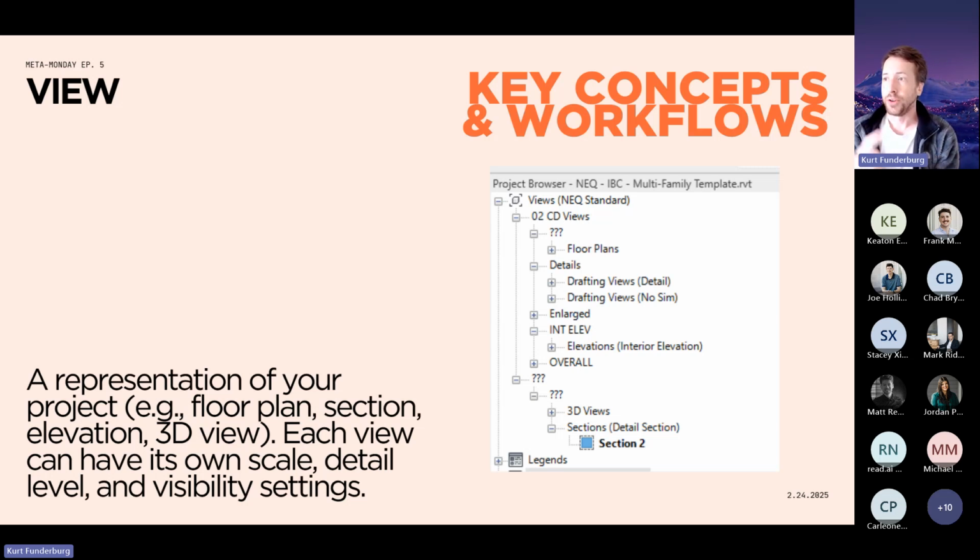And so when we draw a section, we're trying to draw a section line. We can jog the section if we wanted to. And then that allows us to literally cut the model and see what is modeled to where we can add information to it. It allows us to quickly create these drawings or the layout of space so that we can begin to understand what more needs to be done.